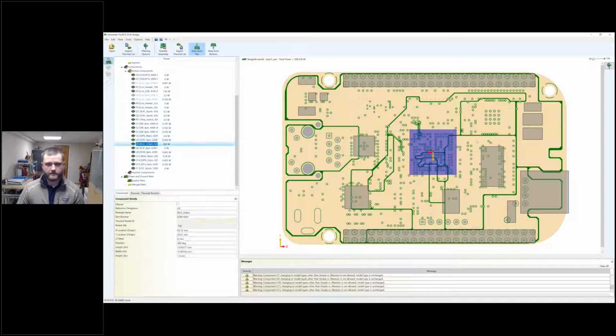And our big one here is this central IC that produces 200 watts. There are different types of models for these ICs, from very simple volume thermal loads to, in this case, a 2 resistor model. FlowEFD also has the ability to use an N resistor model.